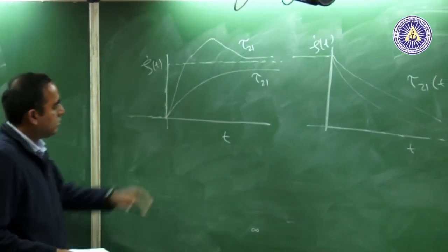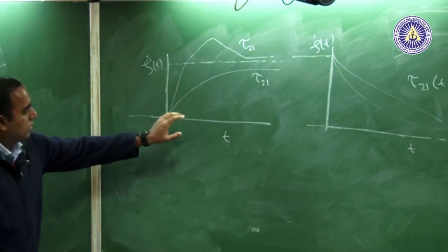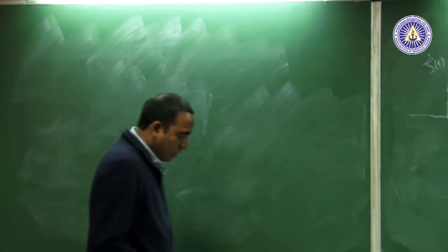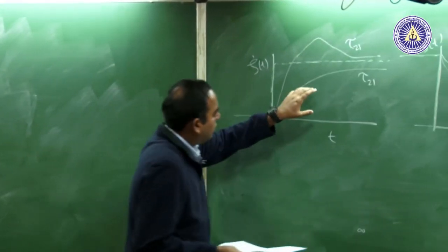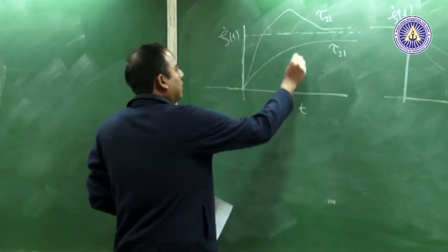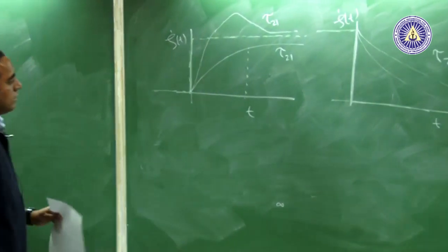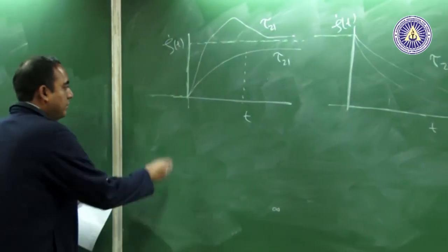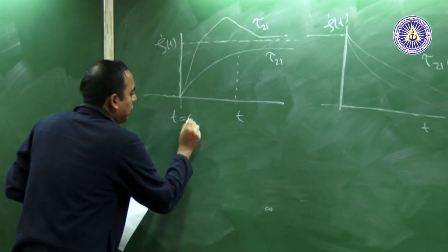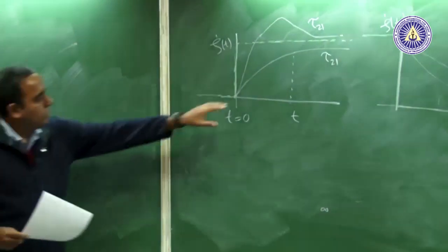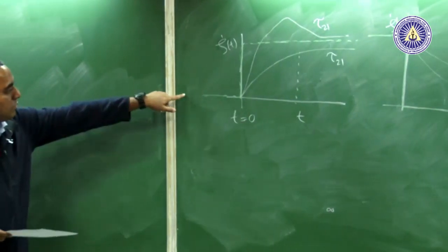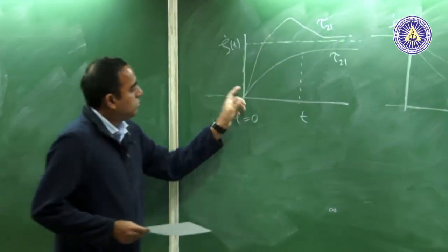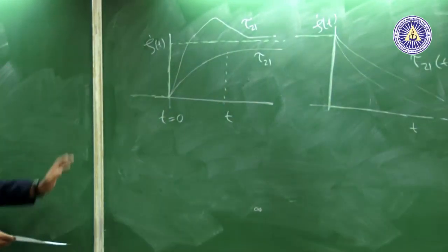They try to understand it in terms of memory, in the sense that they assume the fluid has some sort of memory, which means that the shear stress at a certain time, let us say at this time, which is far away from t of 0 when the shear stress growth started, the fluid will still have some memory of the fact that there was no shear stress before t 0. So, this is true all over the place for all times.